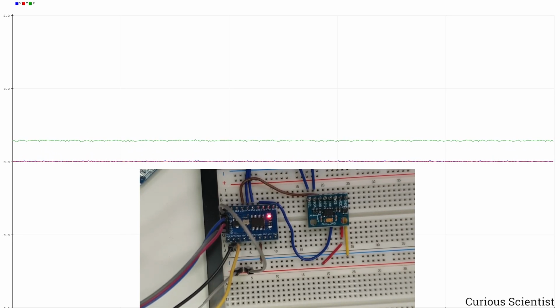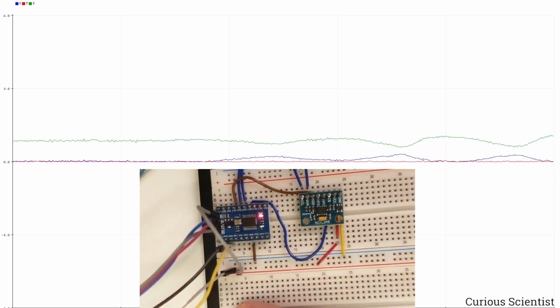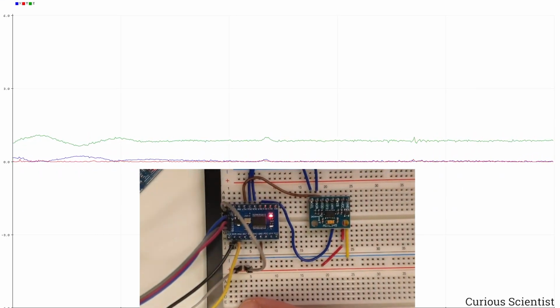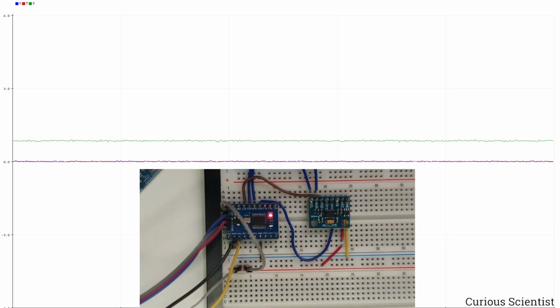And you can do very interesting projects using them. You can use them for maintenance, you can use them for detecting failures in bearings or whatever moving things, and so on. So now, as you can see, we developed the working code using SPI communication and using this ADXL345